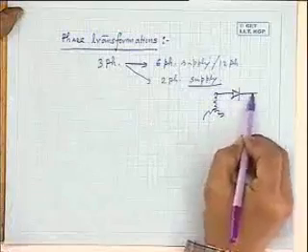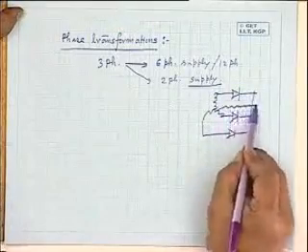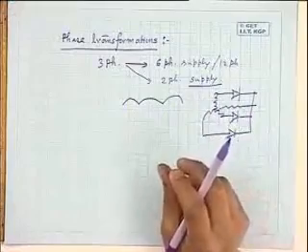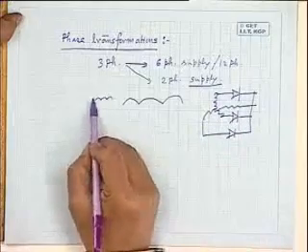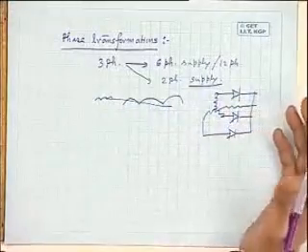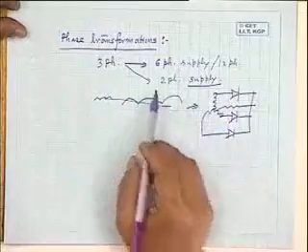You have read about rectifiers or converters? Bridge rectifiers? Three-phase rectifiers. A three-phase supply you use. Now that voltage ripple can be made more like a DC if you have a six-phase supply. See, in a three-phase transformer, I will quickly tell. If you connect like this, you get a three-phase voltage, rectifiers, diodes. This is the load. What will be the ripple voltage? Like this, three-phase voltages will be there. Now, if you increase the number of phases in a rectifier converter circuit, then the voltage ripples will be like this. It will be a smoother DC. There it is necessary sometimes to have a six-phase or 12-phase supply voltage.